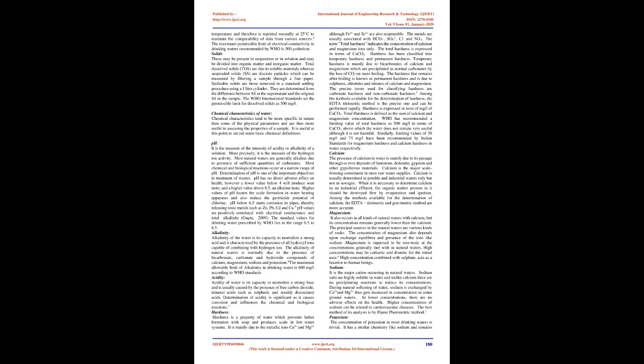Similarly, limiting values of 30 mg/L and 75 mg/L have been recommended by Indian standards for magnesium hardness and calcium hardness in water respectively. Calcium. The presence of calcium in water is mainly due to its passage through or over deposits of limestone, dolomite, gypsum, and other gypsiferous materials. Calcium is the major scale-forming constituent in most raw water supplies.